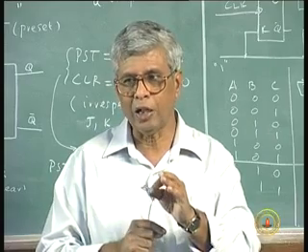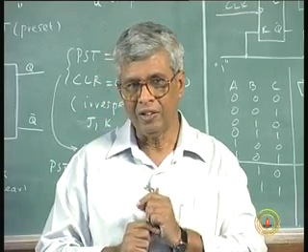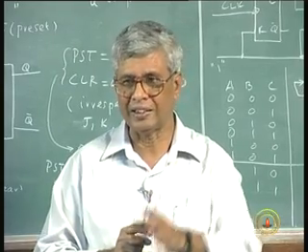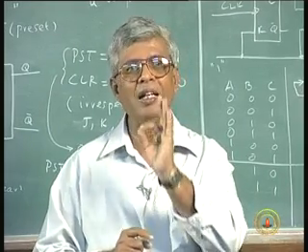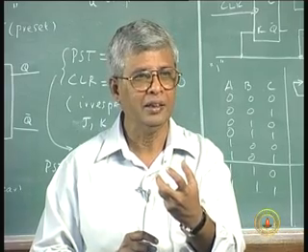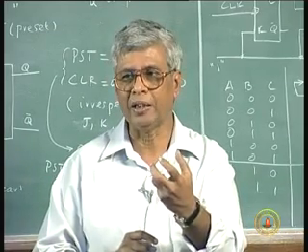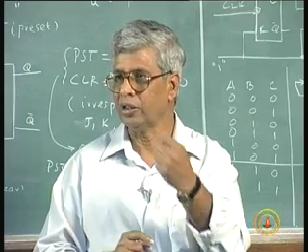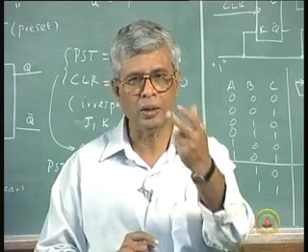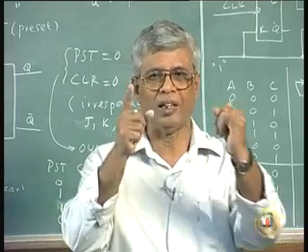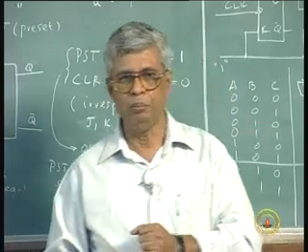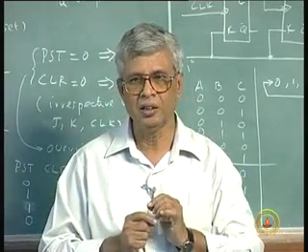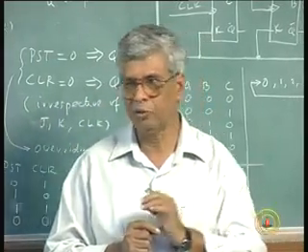So, really I should start looking at 6. If I want to terminate at 5, I should wait for 6. As soon as 6 is reached, assuming there is no delay involved in the clearing process, I clear all the flip flops, so it starts from 0. So, it will go from 0, 1, 2, 3, 4, 5, even 5 will last for the entire period of the clock, and the moment it becomes 6, immediately I will clear it. So, there will be a small glitch. I referred to glitch in one of my previous lectures.